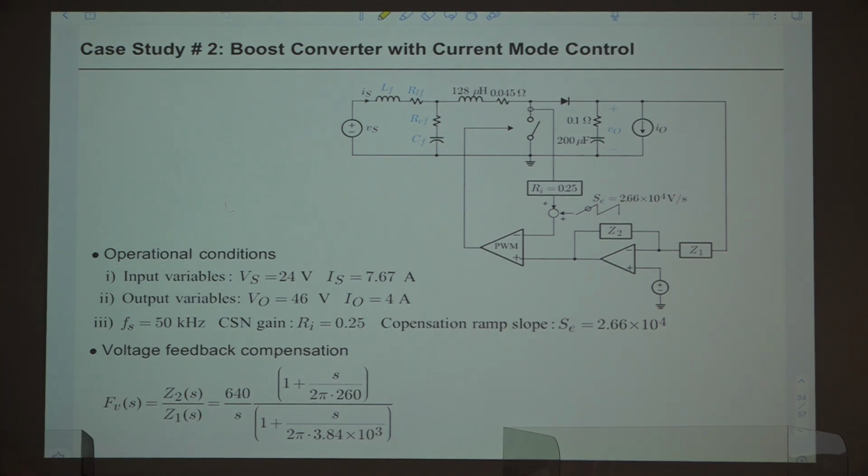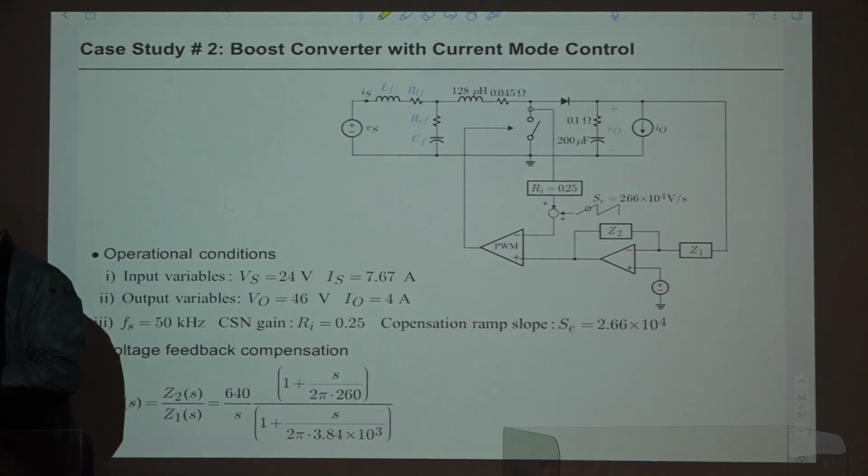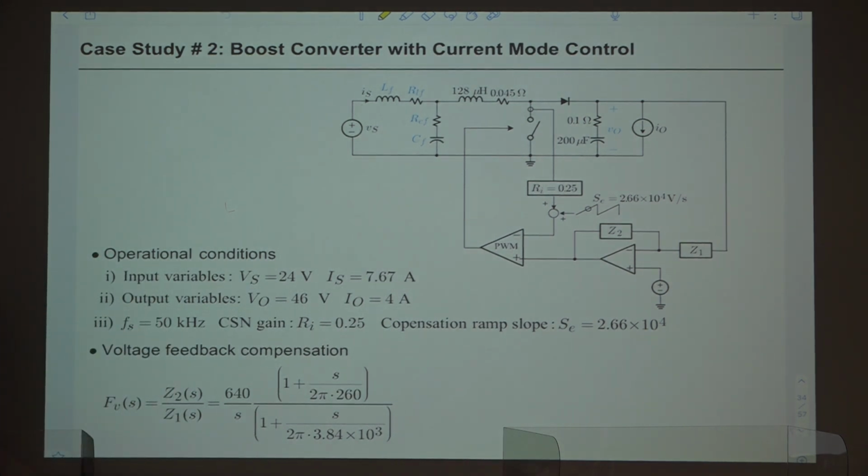The reason for using the boost converter is that it shows the impact of input filter interaction very clearly and interestingly. And when voltage mode control is concerned, all three PWM converters are the same in terms of the shape, pattern and output of input filter interaction. So we go a step forward to the current mode control.